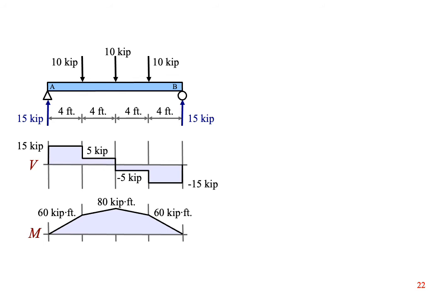The beam with 3 point loads produces a circus tent shape with 3 peaks. The maximum peak is at the center load. We said before that if this beam fails in shear, it will fail at the ends. If it fails in bending, it will fail in the middle.